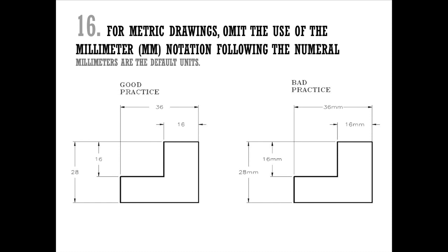Rule number 16. For metric drawings, omit the use of the millimeter mm notation following the numeral. So just like inches, we're not going to specify for every dimension what unit is used. This will be specified in our title block.